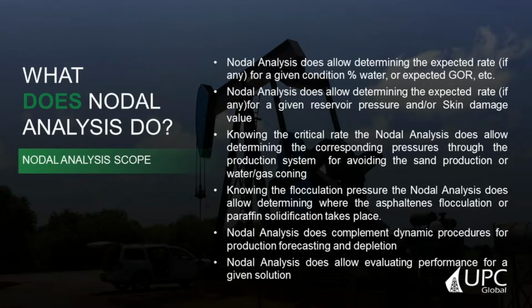Nodal analysis does complement dynamic processes for production forecasting and depletion, meaning that by itself it cannot do it, but it can assist other processes, such as material balance, to do this task. Nodal analysis does allow evaluating performance for a given solution. It does not provide a solution, but given a solution, I can evaluate the performance of that solution.